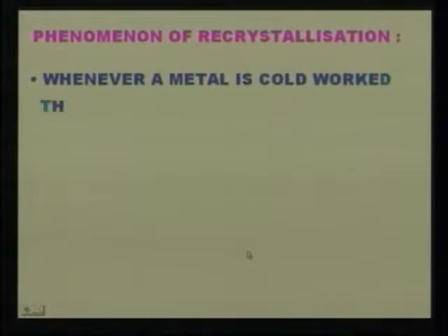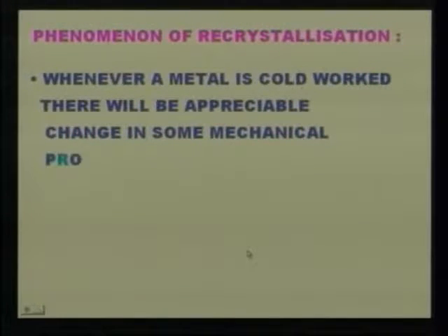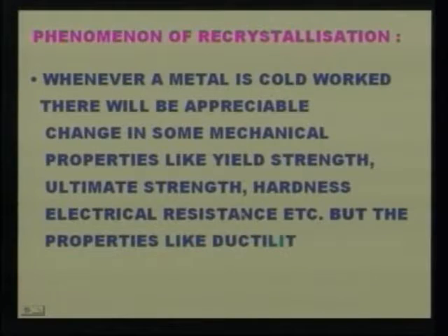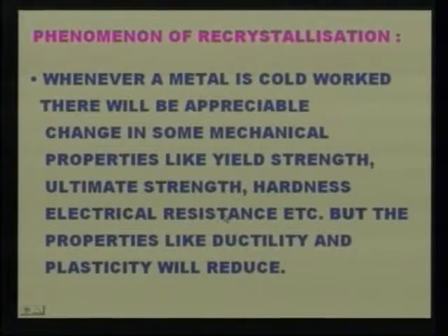Now let us learn about the phenomenon of recrystallization. After solidification, local strains and local stresses are stuck between the crystals, which are disadvantages in applications. To improve the mechanical properties, you have to do the recrystallization process.